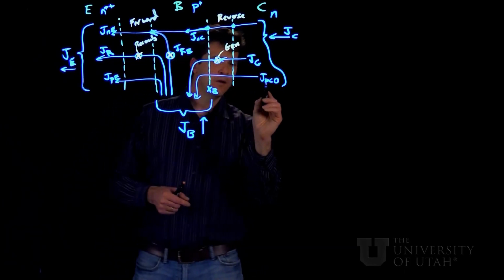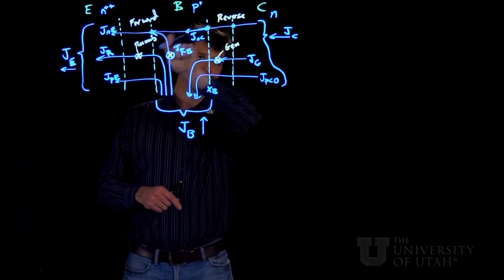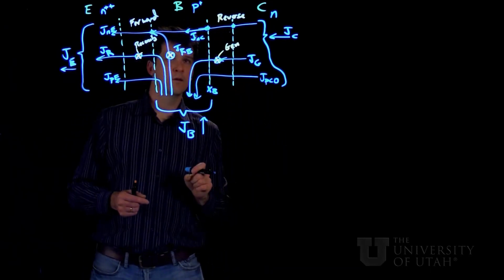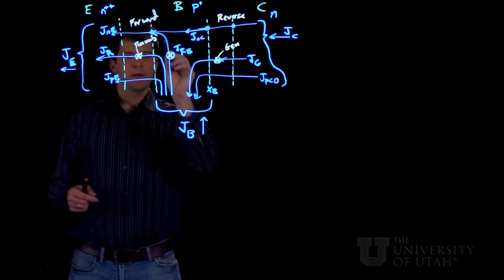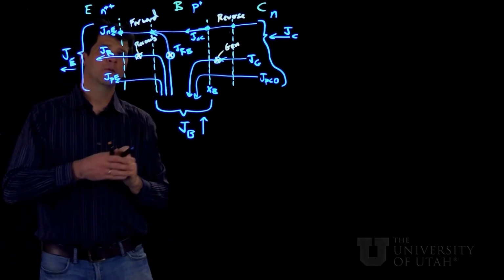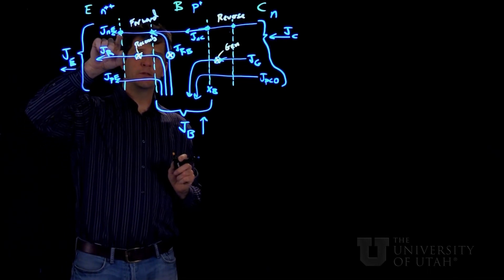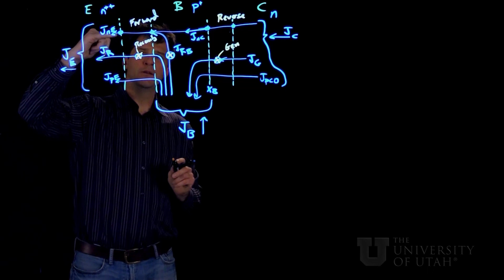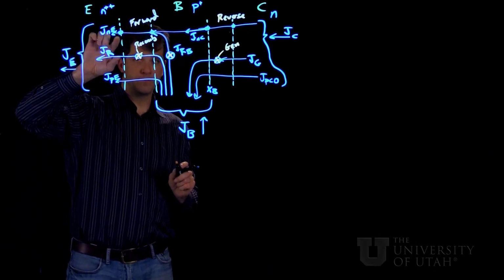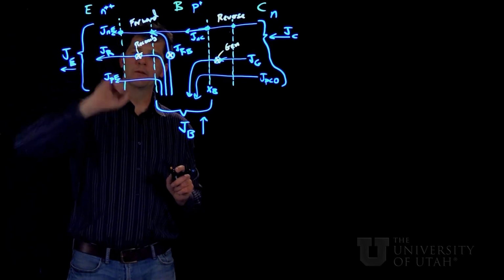Then we have the back injection current. This injection of, if we're injecting electrons this way, it means we're injecting holes this way. So those are considered to come through the base. And then on this side, likewise, at this point right here, we can evaluate the current, which is electrons injected into this forward biased junction, and because of that, they produce a current going this way, and we're going to evaluate it right here at this edge.